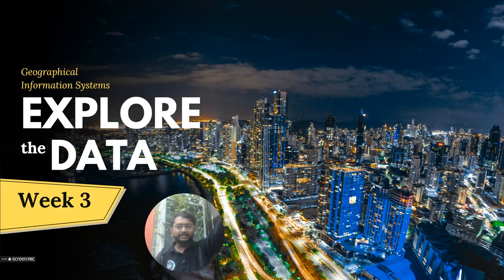Okay, anything else? Cadastral maps, topo sheets, and satellite images from private sources. Urban ward map. Yes. Okay. Then some of the other applications are like someone did a research and published a map, and you want to use the same thing, but you do not have the data, or that person is not responding, or that data is not available. So the best way is to georeference those data.